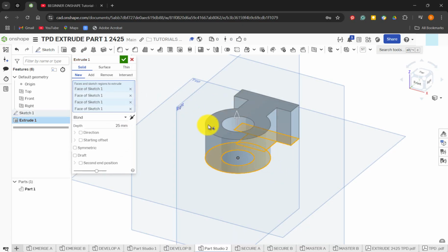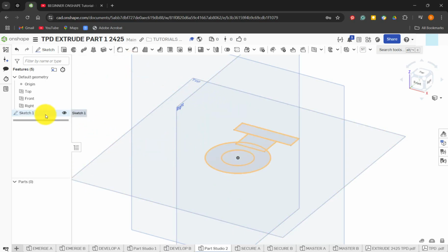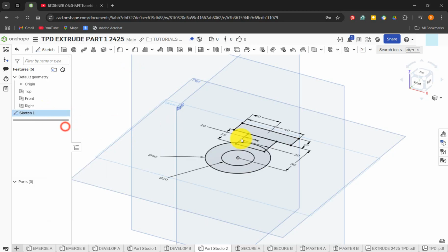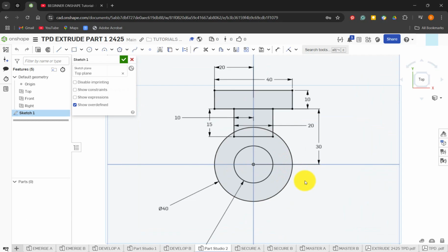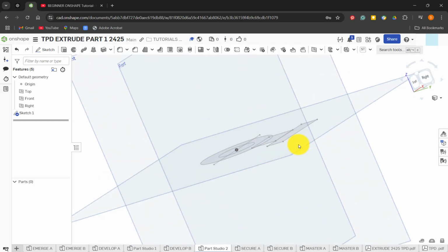However, I want to remove that front bit there. I could save this and create another sketch on the top or bottom and cut it, but I want to do this in one sketch. So the mistake I made, if we go right back to here and edit it, is I haven't sketched a line that is snapping to that center point. I'm just going to do that right across like that. I'll click escape, and we're going to save that, turn it around.